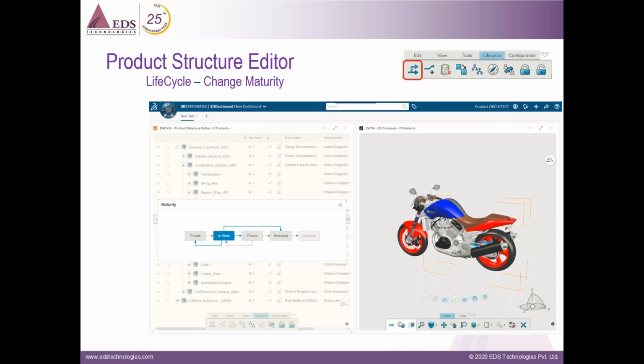That means that the life cycle process of a given assembly can be controlled, and we can do locking and unlocking. As you can see on the screen, we have 5 different stages, starting from work in progress to frozen, released, and then obsolete. We can make use of a default workflow process or your own workflow process. We can set that, and then move this particular component or assembly through this life cycle process. And this change of maturity levels can be managed and controlled through any device.